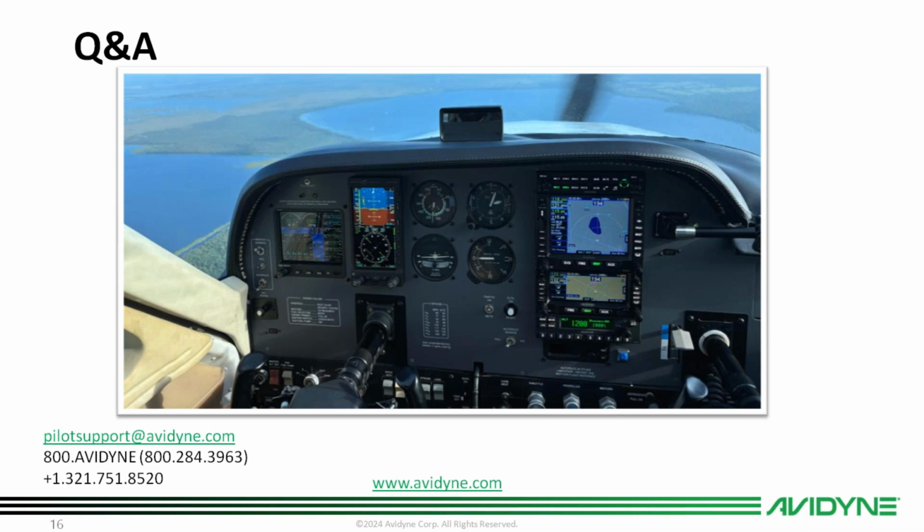Is the G5 supported? I think we talked about that. Yes, it is. Will the VNAV work in the GFC 500 when connected? That's a good question. We have en route VNAV and we have the approach VNAV, which is advisory only for now. I think on the G5 it'll work. I'm not sure if the GFC 500 will accept that though. It might be advisory only for now.